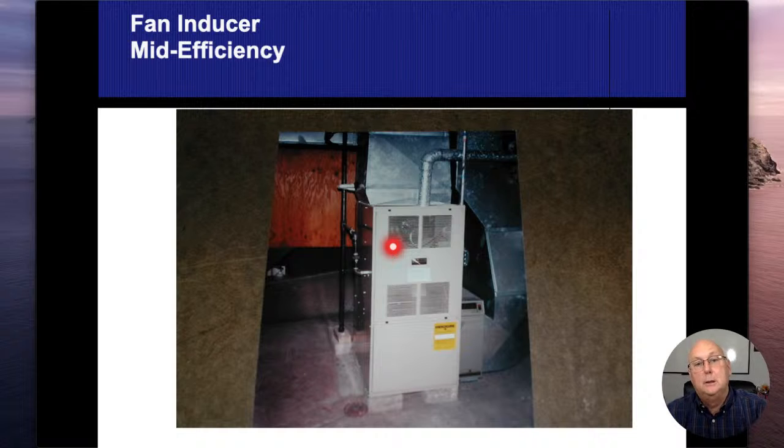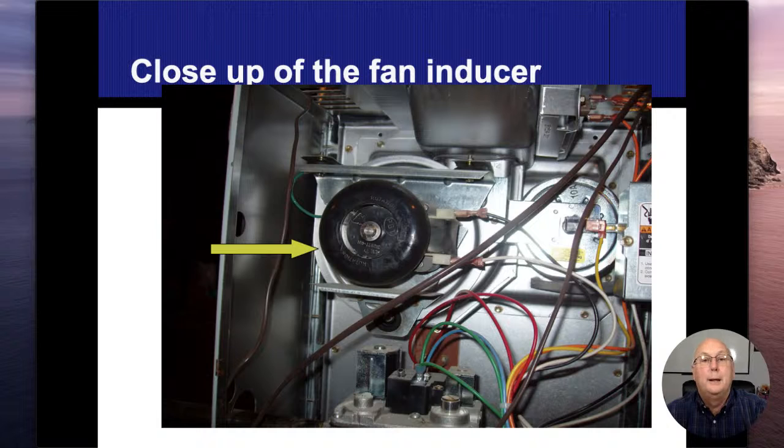If the housing of the fan is plastic, then my vent and vent connector need to be plastic. If the housing of my inducer fan is metal, then my vent connector and my vent need to be metal. Plain and simple. All right. And I'll open that up and see.